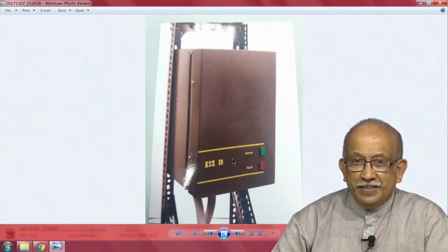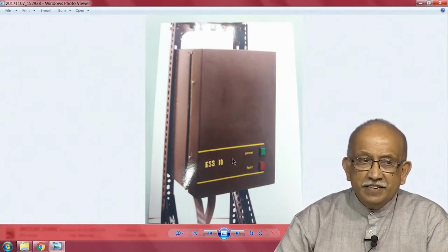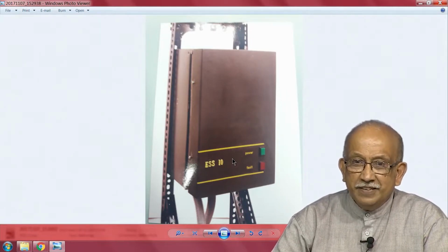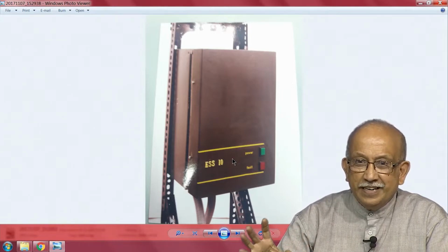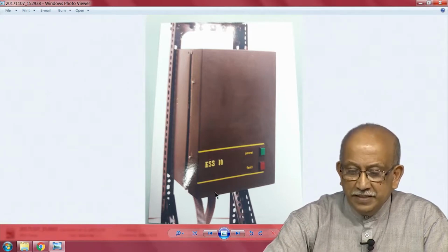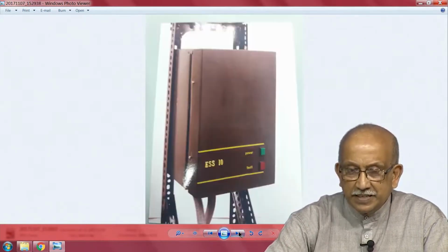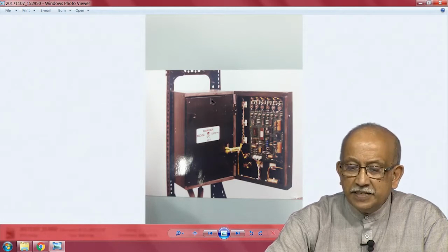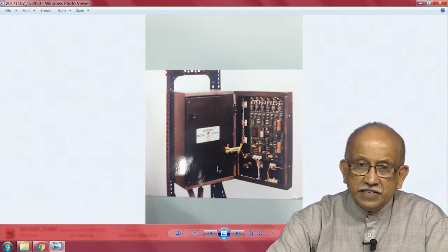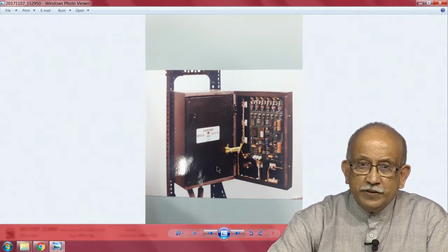So, depending on your various requirements, we have a very neat control of the running of a motor, so that the current it draws is used only as torque and not in heating it up inside or trying to heat up the inertial element of it. The notable feature is that in the front you do not find any of the heat generating components or the high voltage, because it directly works off the 3 phase 400 volt system we have. This 415 is a nominal voltage under which motors and all are classified.